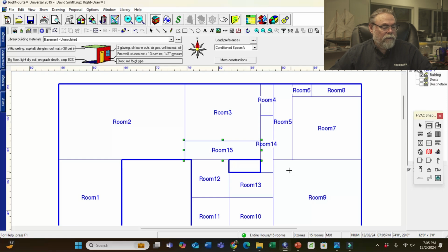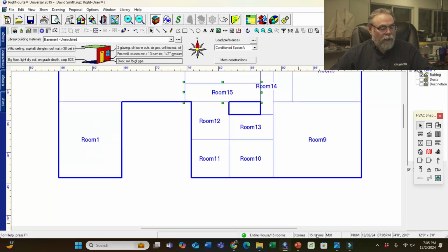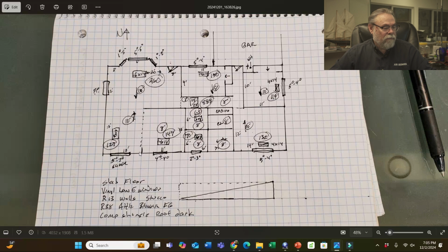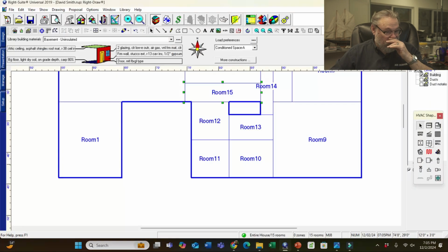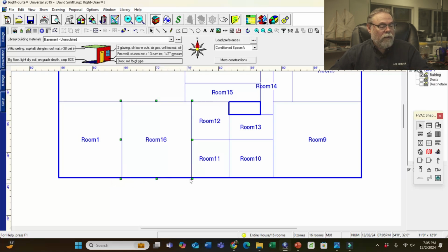And there's other ways to do it. In fact, I'll show you one other way to do it here, over here. So on this last one, all we got left is the kitchen. The kitchen, we can just fill in a space with it. It's 11 feet across, 12 feet tall. So let's do the kitchen. Grab it over here, pull it up 12 feet, come across 11 foot. Well, if I can get it to stay. 11 by 12, release, and the kitchen's done.